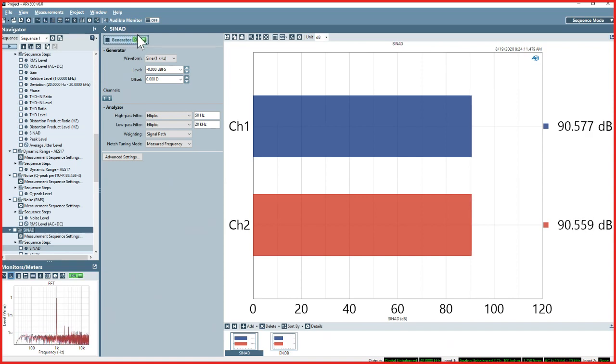So, and especially if we look at SINAD in dB, you'll notice that this is just positive 90 dB instead of minus 90 dB THD plus N. So positive 90 dB SINAD instead of minus 90 dB THD plus N. Now there are some other smaller considerations with SINAD, but that's SINAD. It's just, I probably shouldn't say just, but it's the reciprocal of THD plus N.